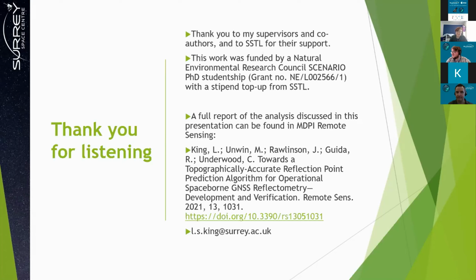And then following on from that, what was the source data for your DEM? So that came from an EarthEnv product, which in turn came from GMTED and SRTM. They provided a whole suite of topographic variables, including slopes and things like that, as well as elevation, which will be good because in the next version of the algorithm that I mentioned, slopes will be taken into account. So it's nice that they'll come from the same suite of variables, so it's all consistent.